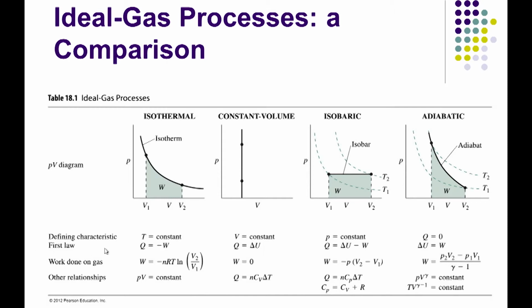That was the general statement of the first law of thermodynamics, Q being heat, W being work. In this case, because the temperature is constant, Q becomes equal to the work, and you can define the work term in terms of the ideal gas law, PV is equal to mRT. Because we know the temperature, we can work it out based on the volume changes as we keep the temperature constant. If there is an isotherm and you are going from volume V1 to V2, you are essentially expanding this gas, and the area below that curve is the work done.